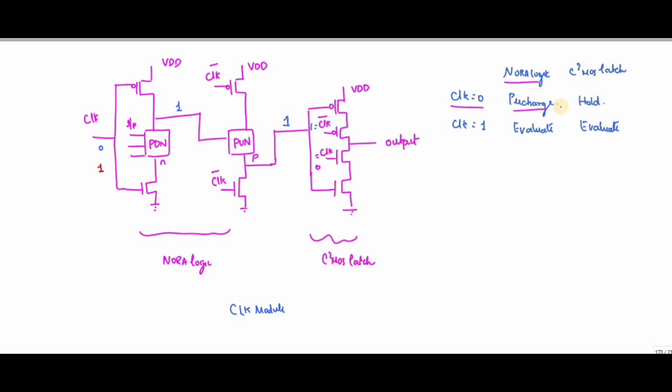So this is how the data is passed in pipeline fashion from module to module. This NORA offers a designer a wide range of design choices, since dynamic and static logic can be mixed freely, and both the clock P and clock N dynamic blocks can be used in cascaded or pipeline form. With this freedom of design, the extra inverter stages required in domino CMOS logic are often avoided.